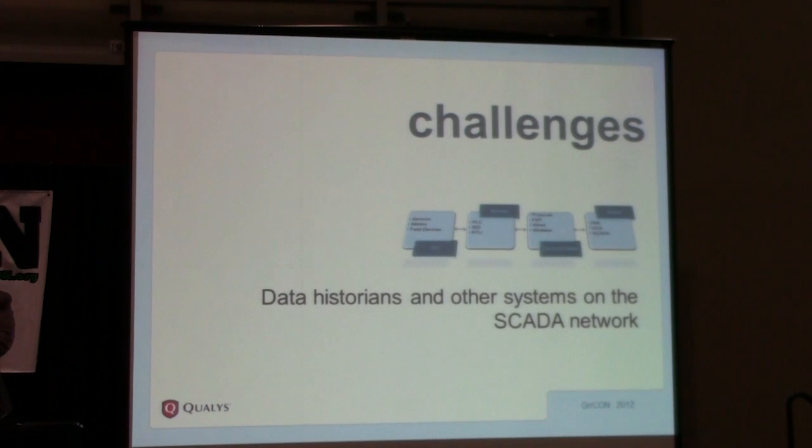In a SCADA system, there are a lot of other things on that network. There are data historians, there are web servers. The data historians are typically databases, which could be Oracle, MySQL, and they are affected by the same thing as an operating system is. Oracle releases patches, MySQL releases patches. Do you apply these patches? Does your SCADA vendor really tell you if it's safe or not to apply this patch?